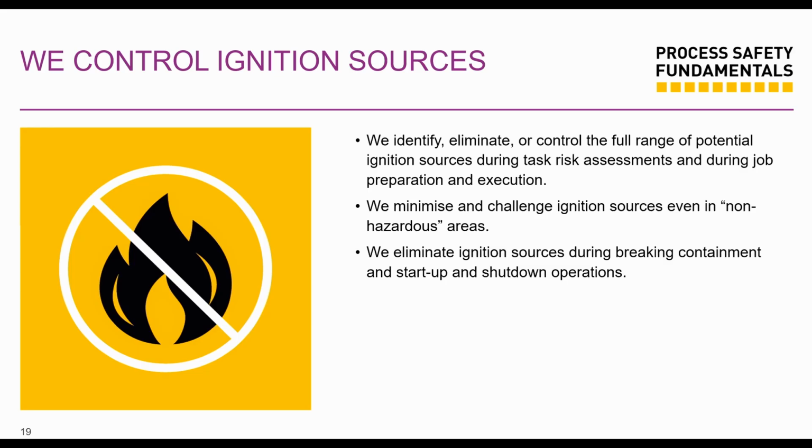The seventh is we control ignition sources. Very, very key. We do our hazardous area classification, make sure we have the right equipment in each area of our hazardous area classification, that each piece of equipment is rated and designed for that hazardous environment that we're putting it in, its zone 1, zone 2. I should actually do a video on hazardous area classification. I think that would be cool.